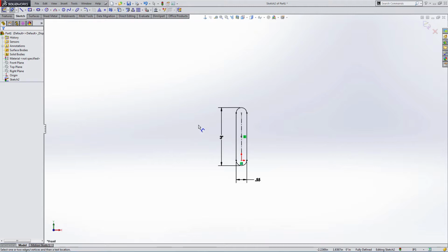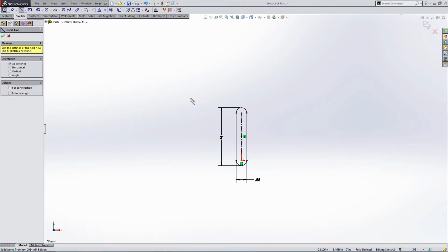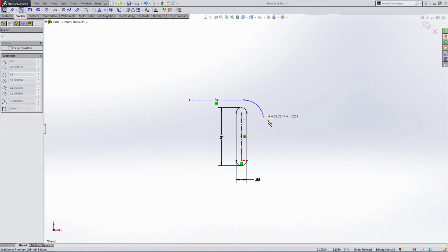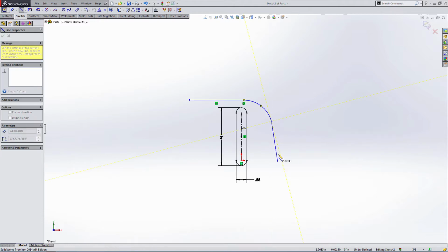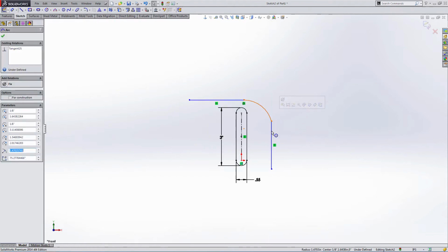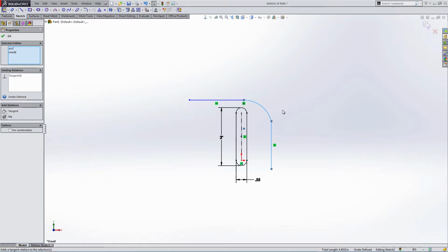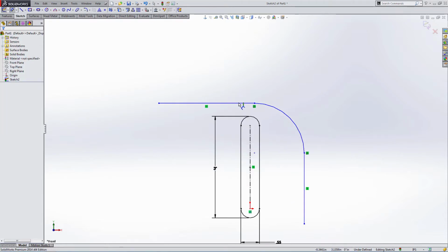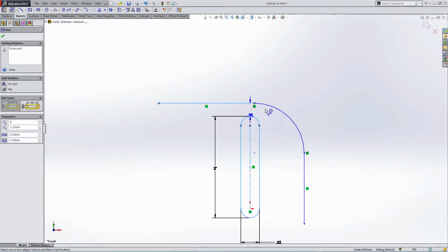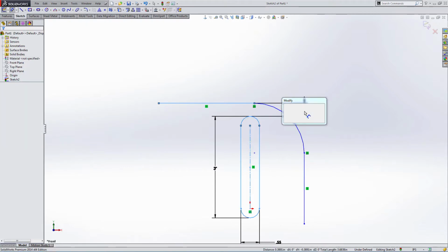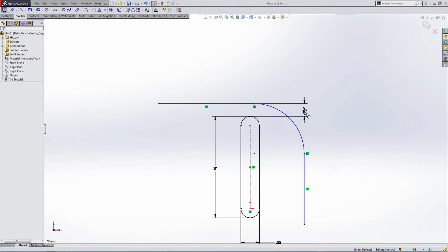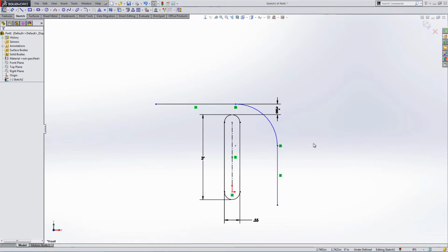And there are times where maybe you've got a shape that's passing by. Let's say it looks like this. And, you know, maybe it comes like that, and like this. And we want those to be tangent. Your shop guy's probably going to want to see what this distance is. He's going to want to know that there's enough meat there to not have that slot break out of the corner of whatever this might happen to be.